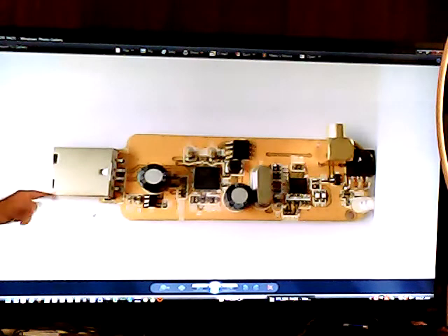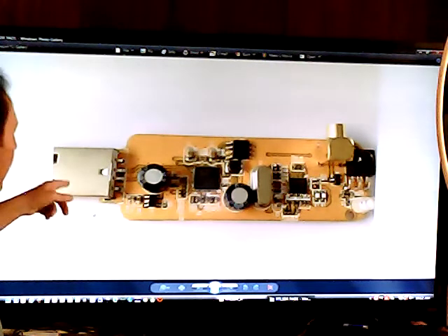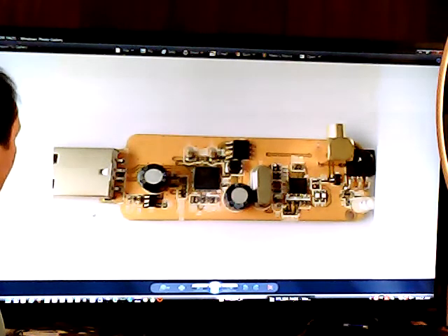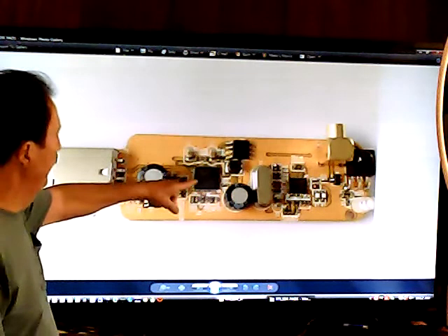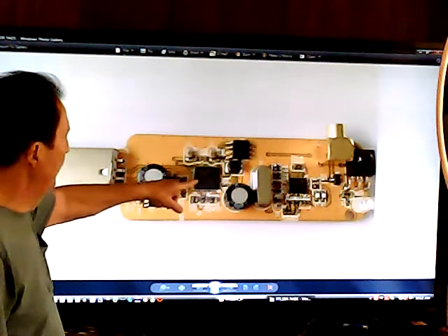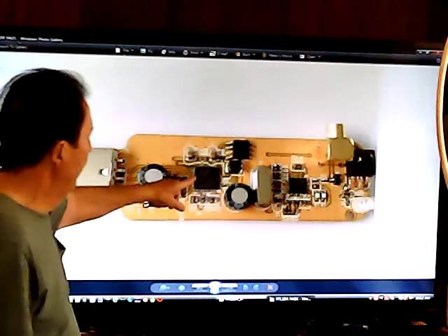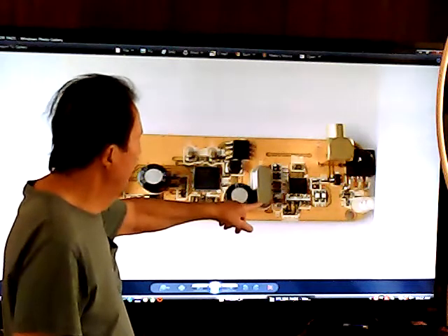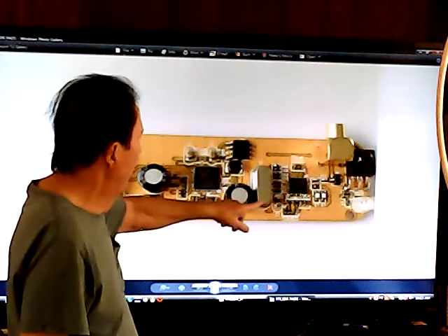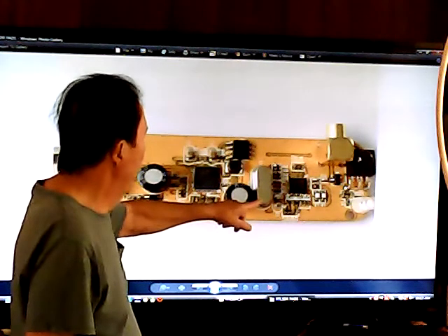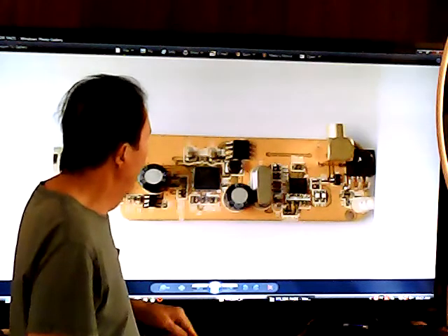This is the TV dongle that you can buy off of eBay for about $15 to $20. And this particular one uses the RTL2832 chip made by Realtek. The earlier versions used a crystal to set the frequency of operation for the chips.